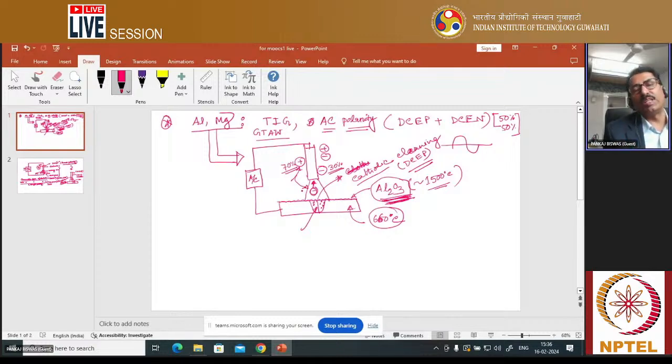That's why for welding aluminum and magnesium, refractory types of material, AC polarity is more popularly used during TIG welding. Why is it used? Because for cathodic cleaning purposes you need more heat generated in the electrode, and to avoid consuming the electrode you need less heat generated in it. That's why you need to use negative polarity as well. So AC polarity is required for aluminum and magnesium refractory materials. You should keep this in mind.